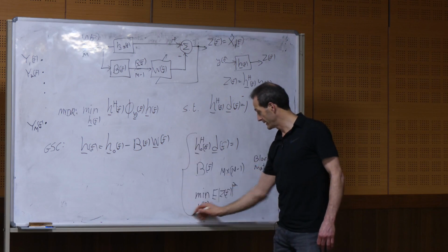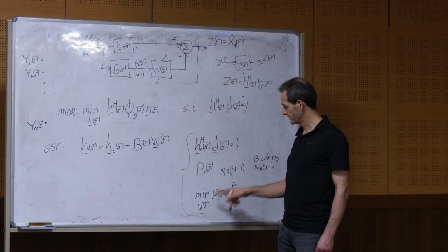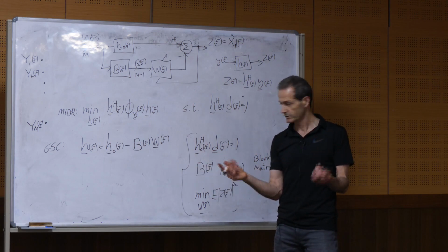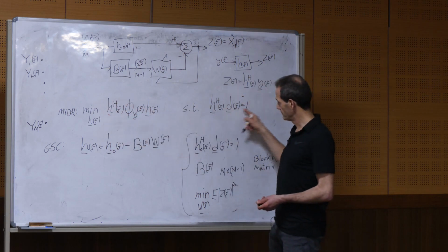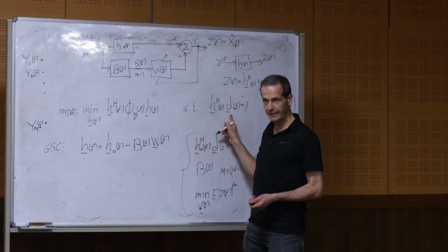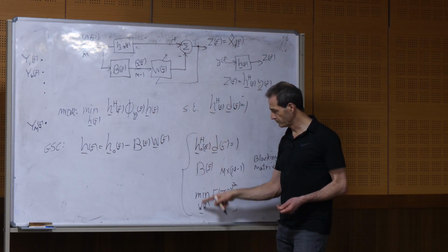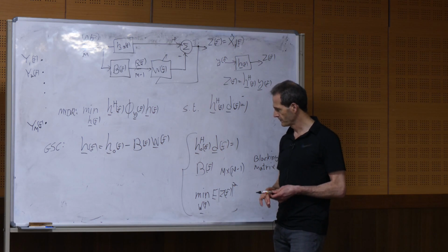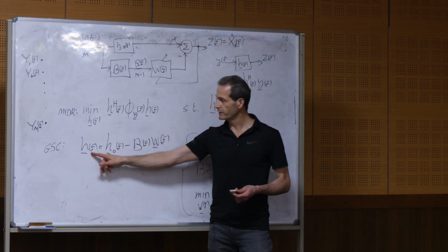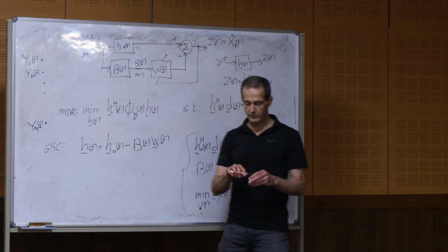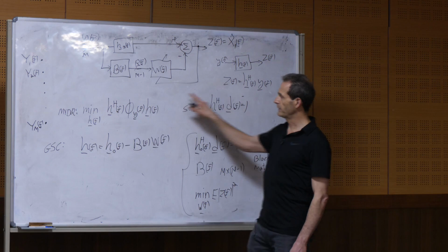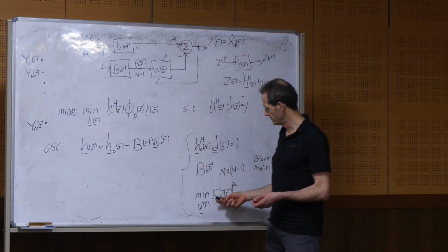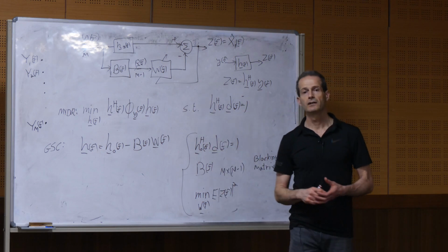So if we solve this, H0, we can solve this. This, we can solve W. B, the blocking matrix, we can find from the relative transfer function. So instead of solving the minimization problem with a constraint, we solve two different problems. One is this, one is this. B, we can derive it. It's quite easy from the relative transfer function. Okay? And then we put it here, so we get the solution. So in theory, the solution of this problem and the solution of this problem is the same. In practice, it's not the same because we have only estimates of the correlation matrices.